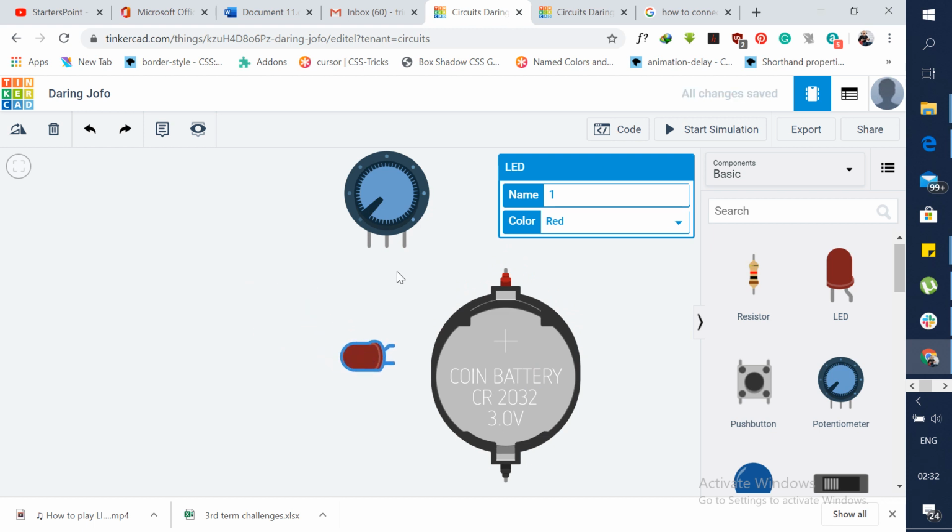It's a sleek one in the sense that we have this terminal. See this terminal 1, terminal 2, depending on which side you want. So you assign one to positive, to the voltage, and the other to ground. Then the wiper is kind of like what varies the resistance, and in varying the resistance, it varies the amount of voltage and the amount of current. So that's what you connect to the LED.